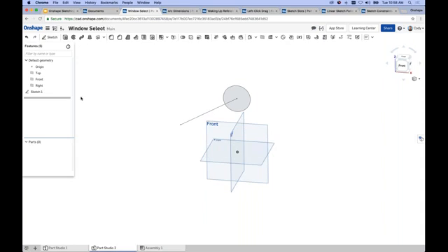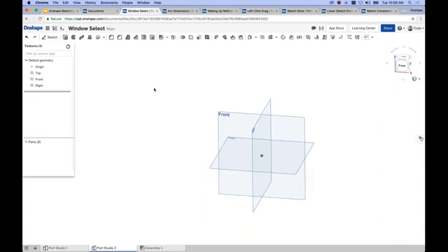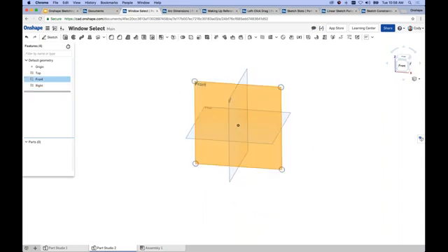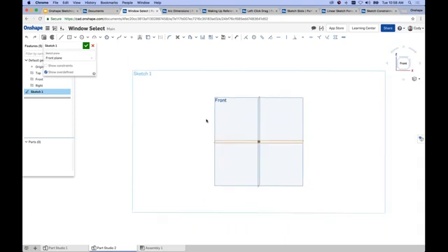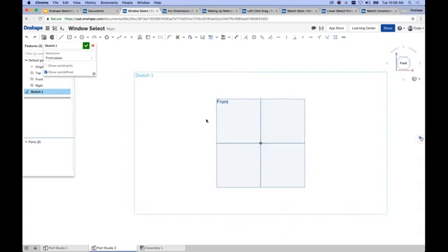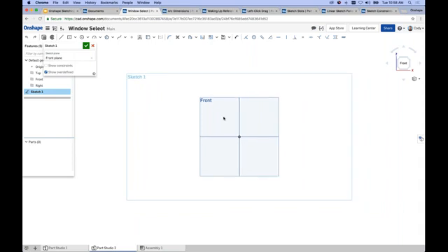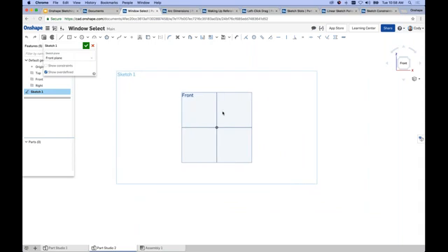And so this is the workflow that I showed you just a moment ago. If I want to start a sketch on the front plane, I left-click the front plane, hit S on my keyboard, click the little pencil, and now I'm in a sketch on the front plane without having to go up to the sketch icon in the toolbar, right? So again, then I could use the N key to go normal to, and I'm ready to start sketching, right? So a big one, again, is the keyboard shortcuts and the S key in particular.